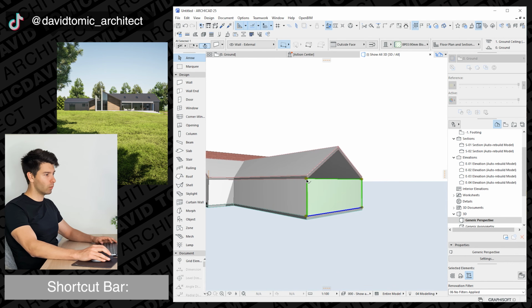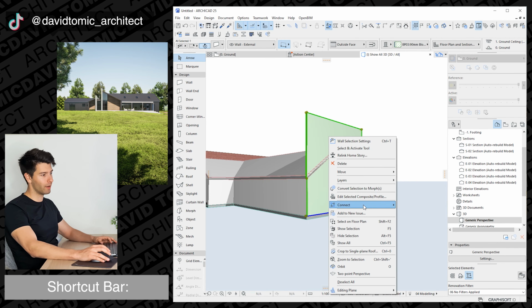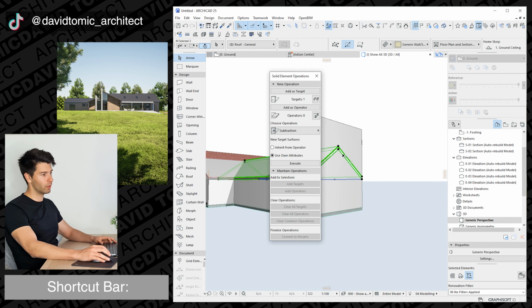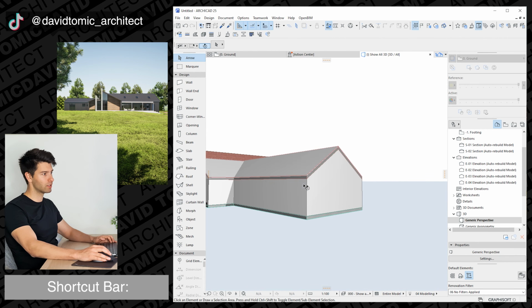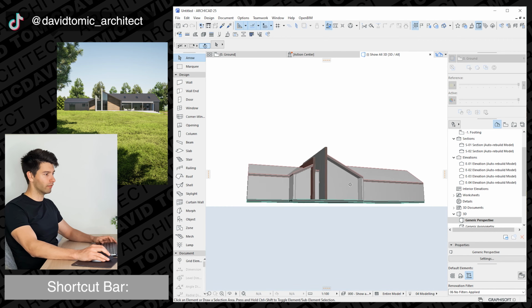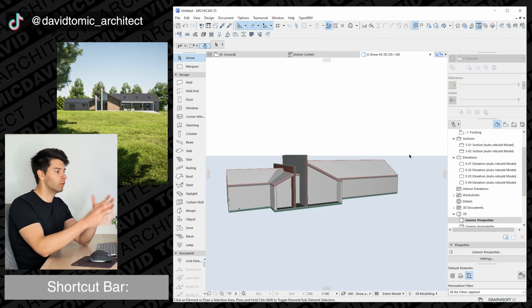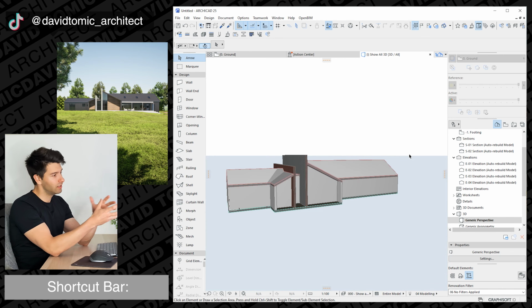Last but not least, there's only one wall that we've forgotten about on the right hand side that we didn't drag all the way past and trim the roof shell to it. So we're quickly going to repeat the same identical steps, trim that roof shell, and finish off the front of our architectural designed home.